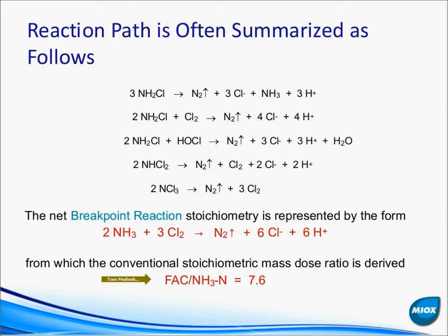That is the absolute minimum of chlorine that you would have to dose in order to drive that reaction all the way through. And in reality, if you're familiar with drinking water treatment, you've probably heard ranges more in the range of 15, maybe even 17 parts per million in order to achieve that reaction. And that gets right back to the complexity of the reaction. So you may not drive every one of those reactions down this nice, easy path right away. You may actually be consuming a lot of chlorine, driving the reactions in some other directions,